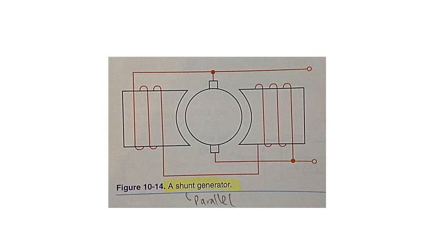The current produced by the armature directly increases the amount of magnetism in the field poles. And this is how the self-excited generator works. The magnetism produced by the armature voltage will increase until the field poles reach saturation, the point where the poles cannot contain any more magnetic lines of force.